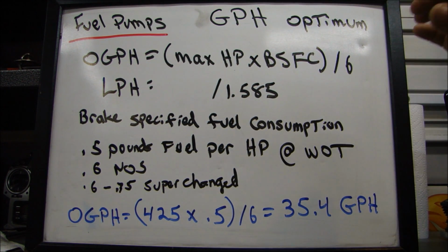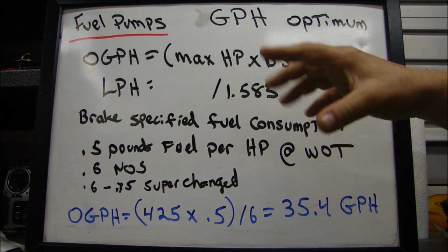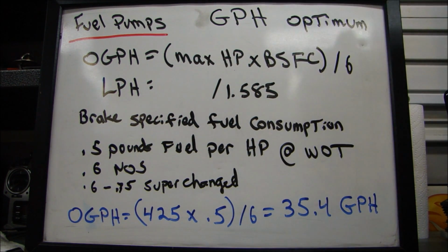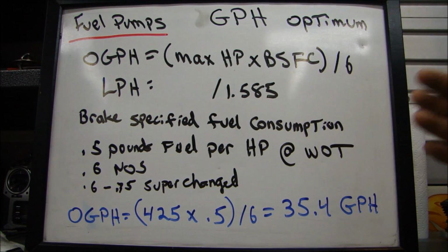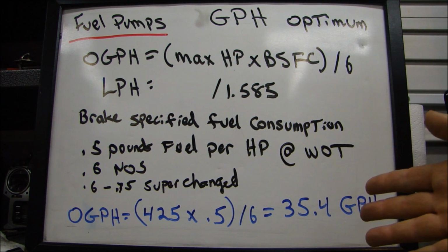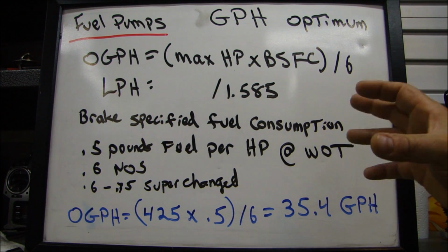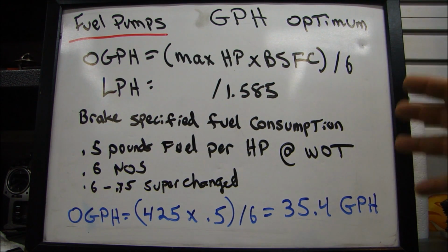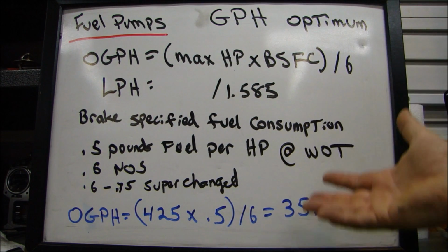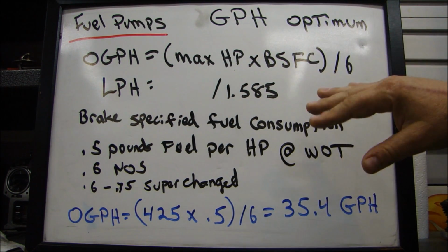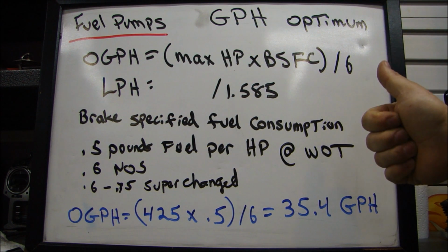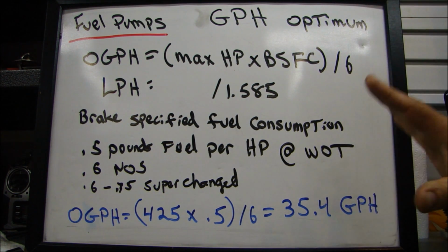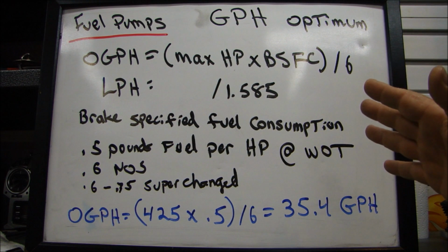Now the difference is pressure. When you have a fuel pump that's feeding a carburetor, you don't need 120 psi. You don't need a lot of pressure. So whether you're choosing the mechanical or electrical, you need to also consider the fuel pressure and its relationship to the volume of fuel it's going to be delivering. And it's inversely proportional: as the pressure increases, the volume will decrease, let's say everything's equal in the engine.